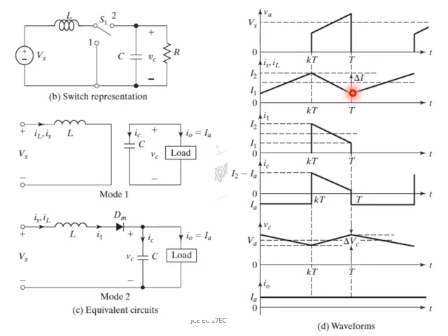If you look at the capacitor now, the current is going in this direction. At that time this current I1 is going to split between IC and I0. So the current which was earlier going like this now reverses, becomes positive, and shares this I1 value, which is equal to IC plus I0.